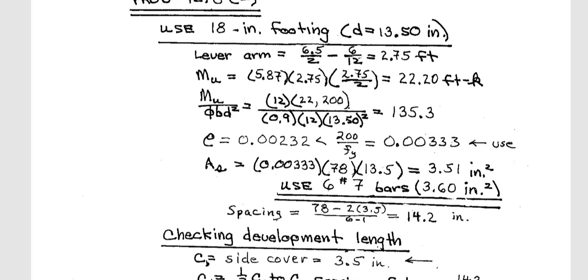So from that table, we will check our rho. So our rho is 0.00232 based on this number. If you go to the table, you will find it. And this value, now you can check with the minimum rho. What is rho min? That you will find in table A7 or A8. A7. So you can check this rho whether it is more than the minimum or less than the maximum. So you can go to table A7 to check this. And they checked it, it is okay.